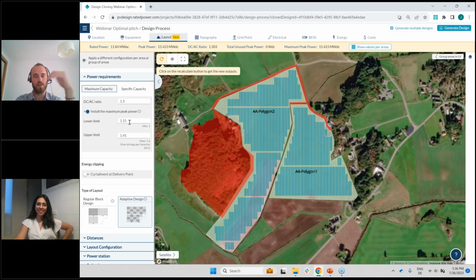If you have low sun elevation, then of course the voltage in your inverters depends on how many modules are connected, how many strings. And if you have a higher DC-AC ratio, then at lower sun elevation angles, so at less irradiation, you can still perform. So I would say, yeah, it has an effect. Sorry, that was the wrong start, but while explaining, I managed to identify it. Yeah, and correct. You actually answered also another question that asked if the optimal pitch depends on the PV module. So 2-by-1, so great one.